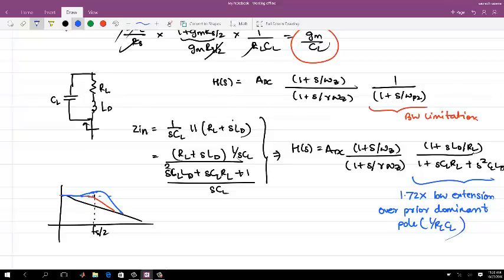So this more peaking which you are seeing right now can lead to over equalization in the channel response, which can reduce your vertical and horizontal eye opening. So more peaking is not always good, and you can check that very well by simulating a worst case vertical and horizontal eye opening. Once you get the CTLE transfer function, you can get an impulse response in your behavioral simulations, and then you can use that to get what CTLE response you want.